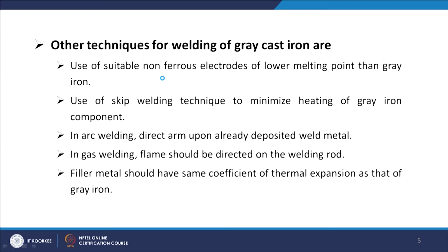We also use the skip welding technique to minimize heating of gray iron components. So, we go for skip welding as well as the back step.